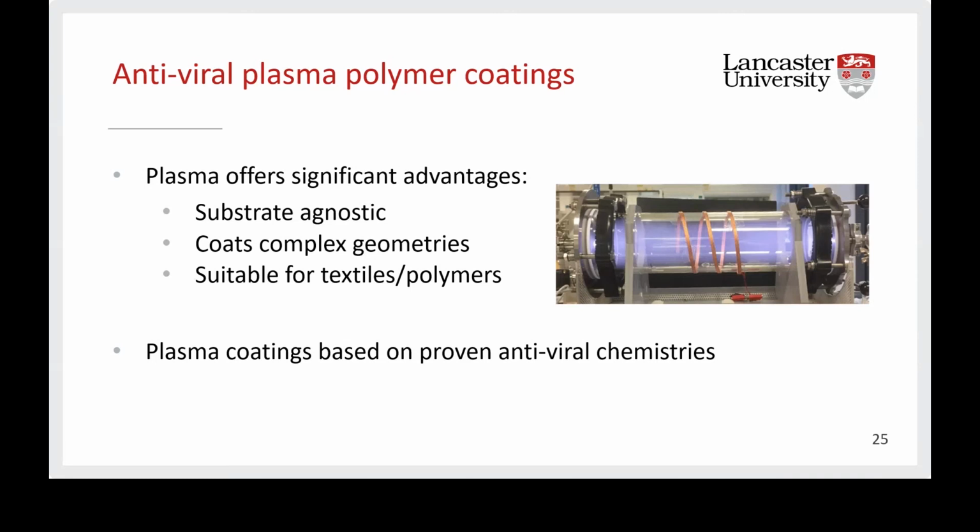and then use the strengths of the technique to apply it to a range of different applications. Currently, we've made a number of different coatings. We've used surface analysis techniques, such as XPS that I showed you a minute ago, to find optimum coating conditions for our reactor to retain the functional groups that we believe are going to have an effect. We've also tested those for stability. The next step is clearly to say, are they actually antiviral?